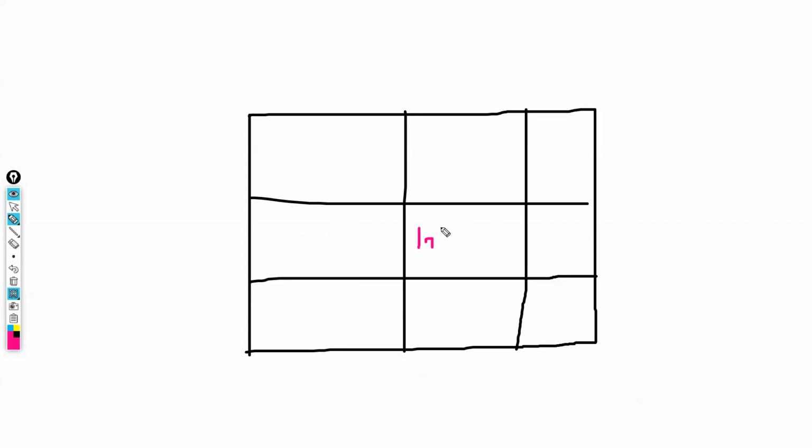But then, when you look at this panel here, this one, here I have a slab, I have a slab, I have a slab, but then on the opposite side, I don't have a slab continuing. So we take this to be, the panel type is going to be, if this is the long edge, one long edge discontinuous.